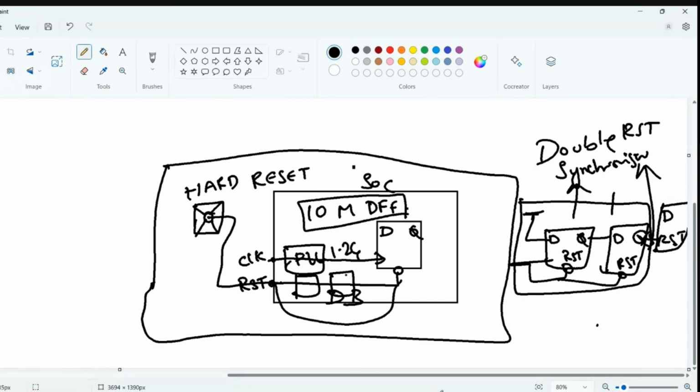In the RTL perception, we have to make sure of this particular clock. There is a clock pin for these flops, right? This flop has a clock coming from the same clock. So you want to synchronize this reset with this particular clock, right? Because clock and reset have to be synchronized so that the reset is not toggling while the clock is coming in. It should be 0, I mean active low, so it should not toggle the flop.